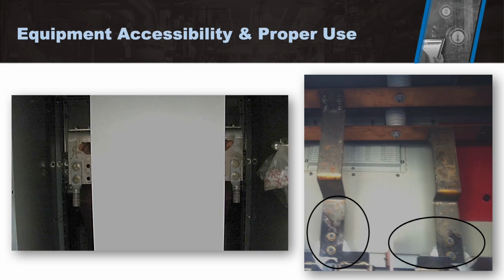And for example, in this image here, the image on the left, you can see that this would be a great place to do thermal imaging. You've got your cable terminations right there in front of you, but this design really didn't allow for it because of how it was built, right? It wasn't planned for it. You can only see two of the terminations. You can only see A and C phase, so B phase is completely hidden.